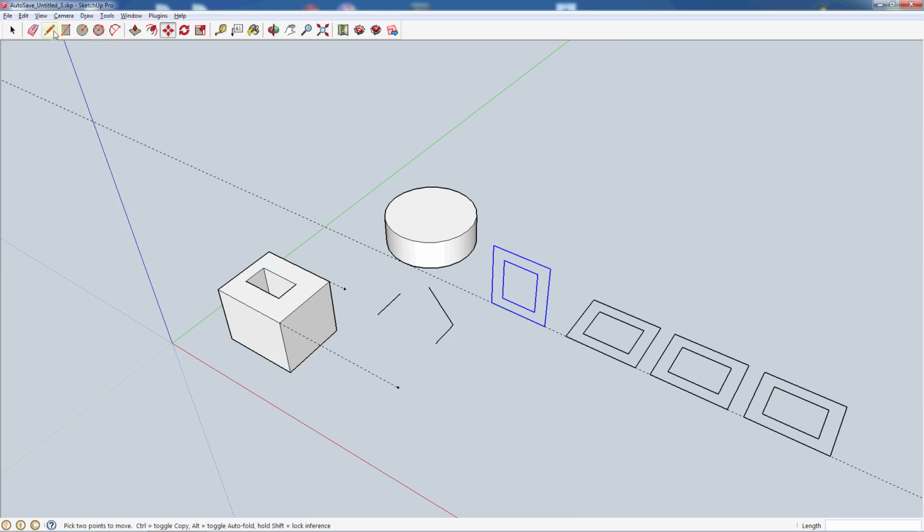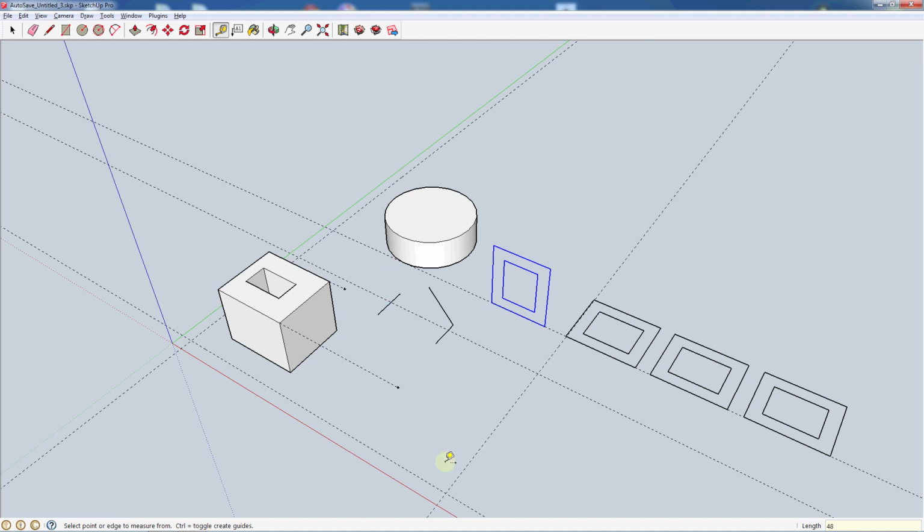You can also create a grid. So if you wanted to create yourself a working area, you could say, okay, come in 2 inches from that edge and 2 inches from that edge, and keep everything 2 inches off of our edges that way. You can also say, okay, I need to bring it up 24 inches from this one, and in 48, and then everything inside this box, you would have working in a 2 by 4 foot area. So that's basically what you can do with the measuring tool.